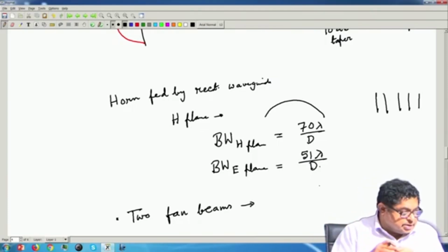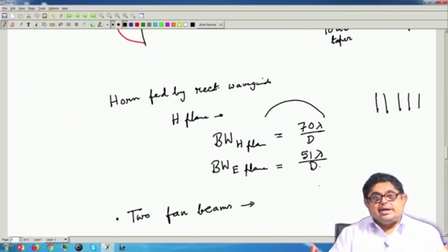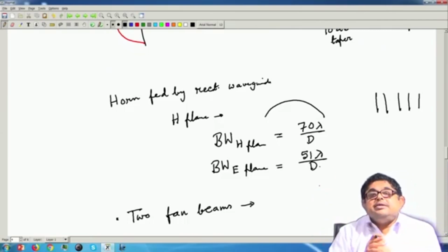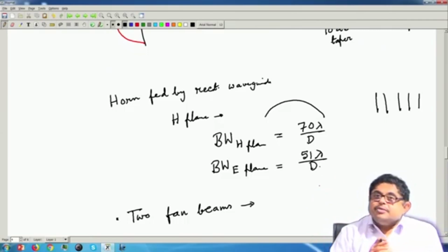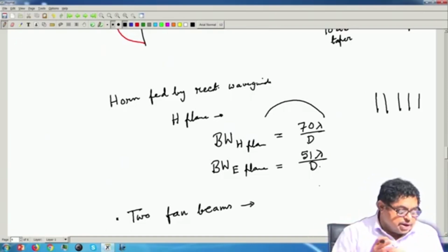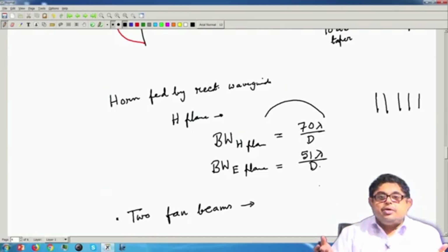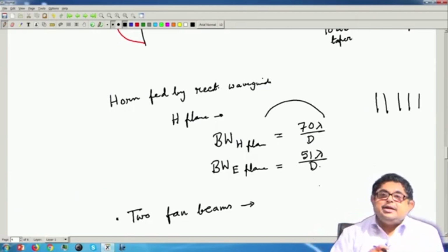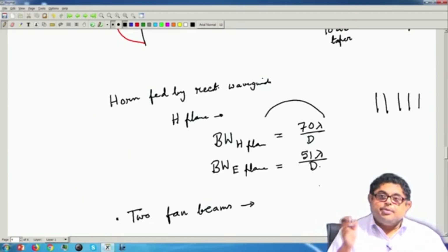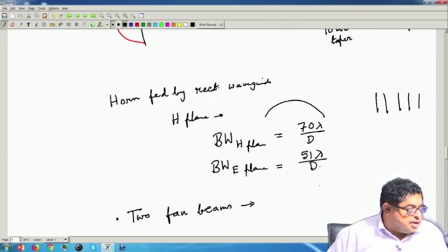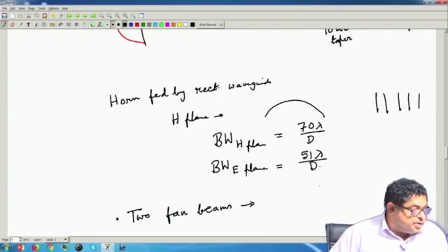If several targets are detected, separated in various azimuths and elevations, then they are correlated according to range. An azimuth echo and an elevation echo having the same range are correlated and assumed to come from the same target. Such radars can acquire many targets at different ranges simultaneously.